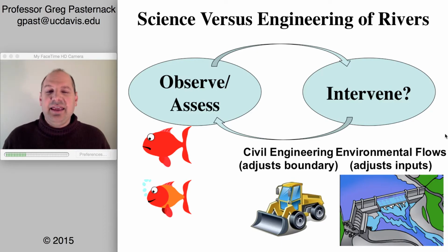So in a simple case like that, river restoration could be as simple as just destroy the road, put the channel back to its original configuration where the road crossing was, both upstream and downstream, given any changes that have taken place, and then put a bridge over it with no piers in the water, just a single span bridge, and get out of the way basically of the river. Of course, that's a lot more expensive, but it would solve the problem. So that's a case where you have a single action that you can identify. You can pretty easily characterize the pre and post project conditions. We understand the science of it. You just have to go and do it.